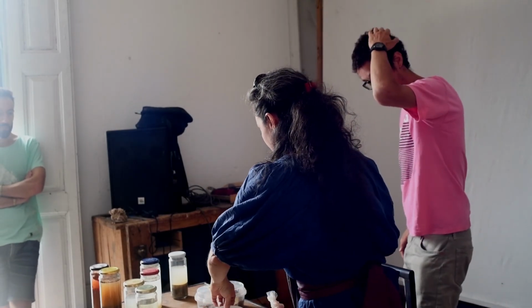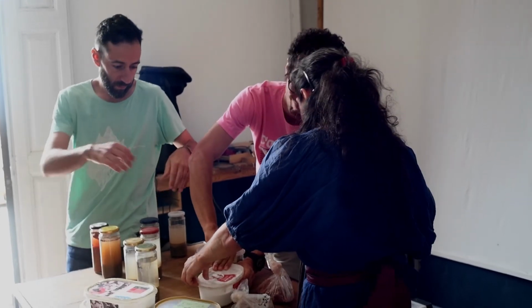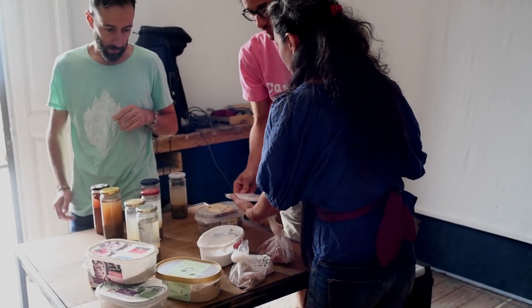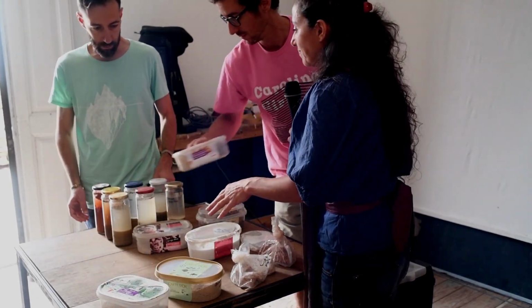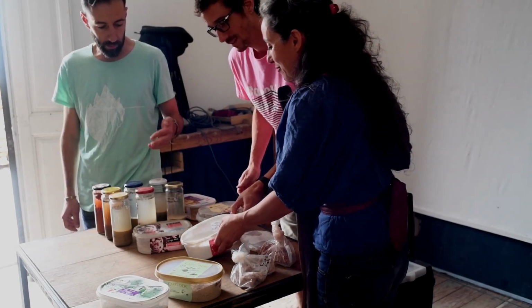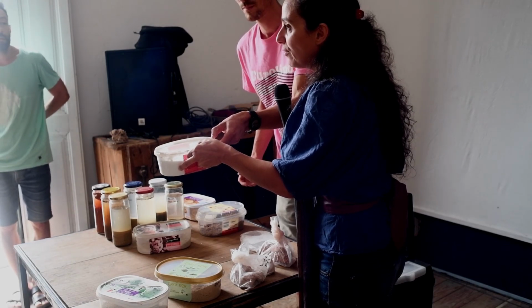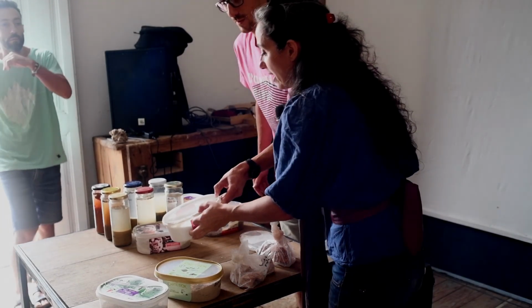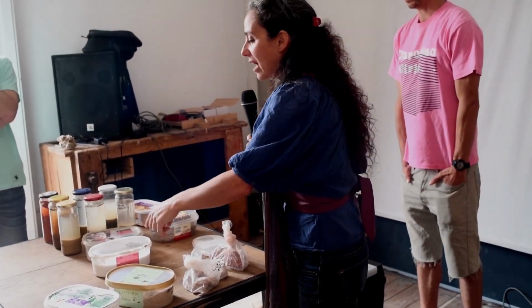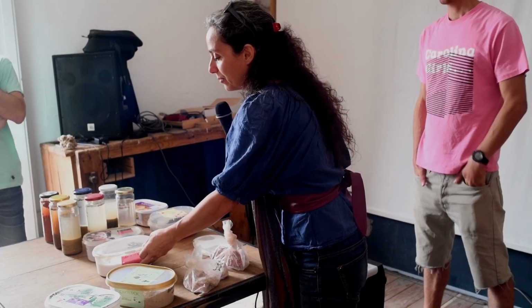I came with something, because yesterday we talked about lime. This is the lime that I told you about. This was stone lime mixed with water, and it was already burned. Right now this is called lime putty, which is really good for plastering. With this you can also make paint, and you can also use it mixed with materials for very good insulation. This is very interesting because it is only water with lime, and the longer it stays there, the better it becomes, because the reaction between lime and water is always happening. So if you want to try it and see what I was telling you about.